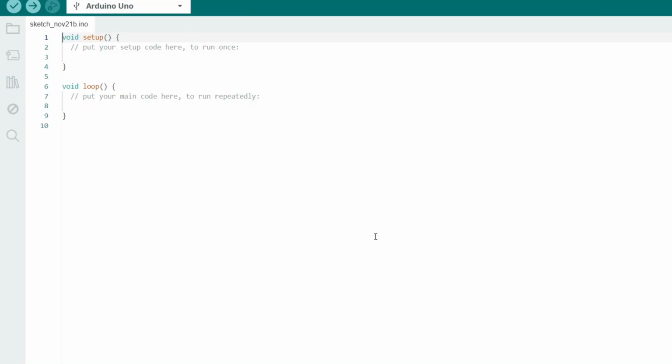Alright, now for the Common Anode RGB LED. The Common Anode RGB LED is a bit different to program. With that one, you have to once again invert. Use the inverse number, like the opposite, I guess. If you wanted to set it to a low, you have to set it to a high.